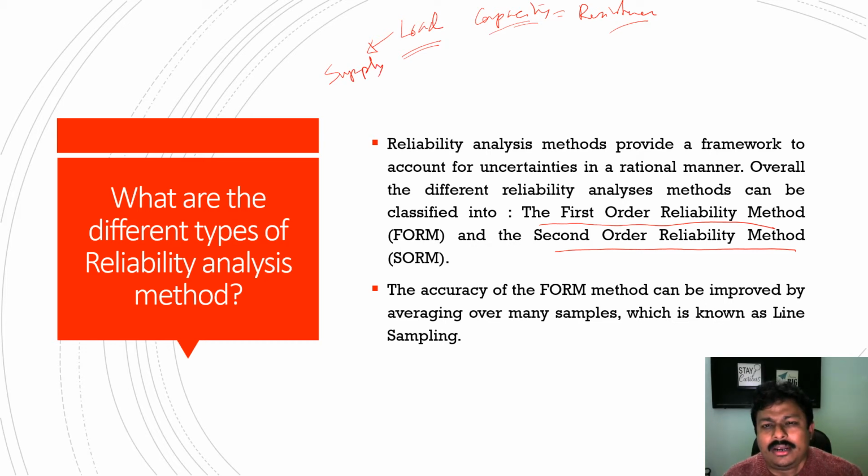Now, if I have the data of this load and capacity for 6 months, the runoff data or the discharge data, or let us take the discharge data. Okay, so the demand for the power which a discharge can generate. Suppose I want 10 kilowatt of power, then how much discharge is required to create this power? That can be found with the help of this equation: rho g Q H eta.